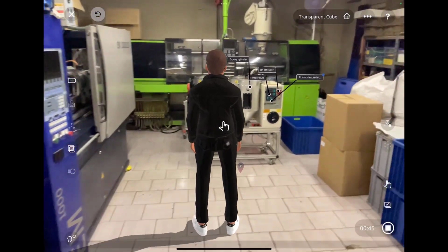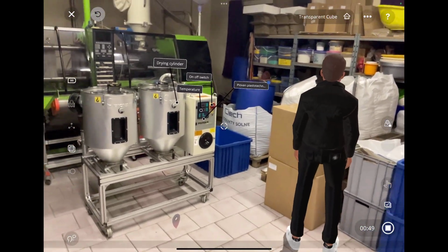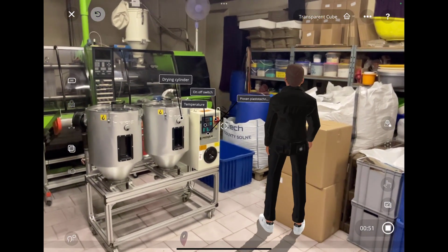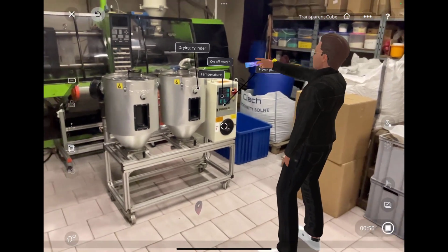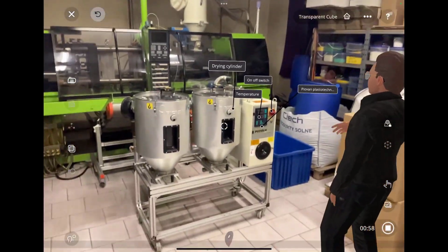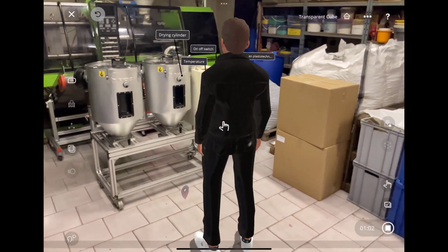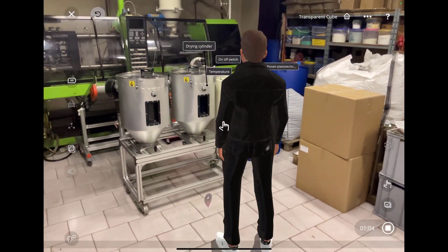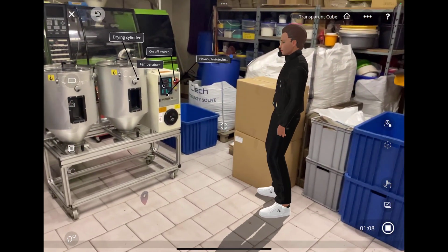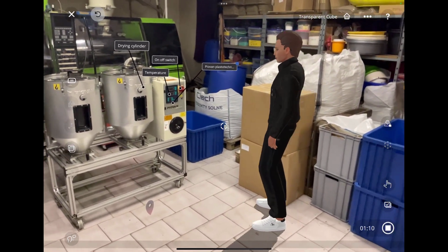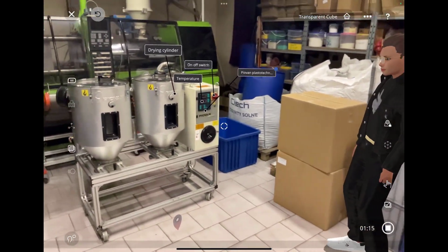Before that, what we need to do is to go and prepare the plastificant materials like ABS, polypropylene or others that can be transported and dry them. So one of the solutions to use could be a professional dryer like this Piovan dryer, which is able to produce the ABS or polypropylene with only 2% of the humidity, which is very important for a future quality of the process.